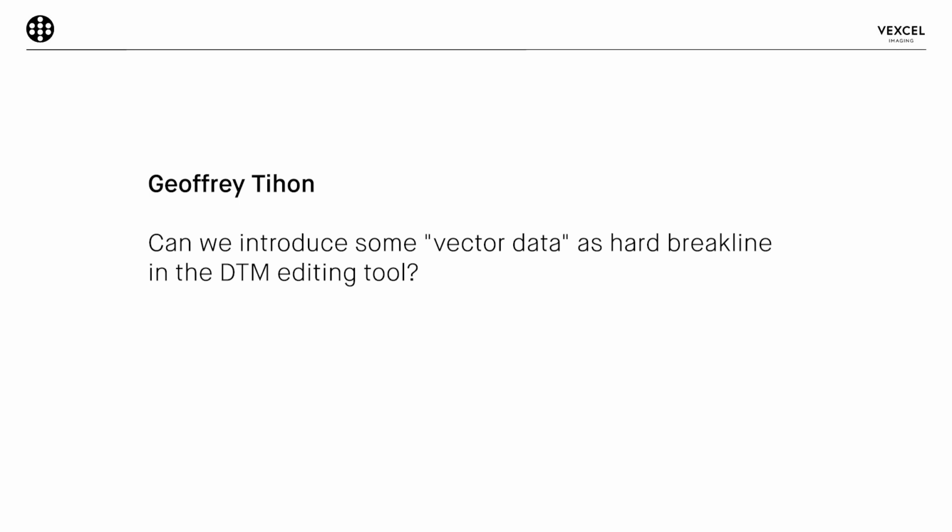And still, we do already support manual creation, manual editing of break lines in the DTM editor. So the DTM editor, as it is available now, allows to modify break lines, to create break lines where needed, or also to delete them. And using these break lines, you can fully modify the DTM internally in the software.